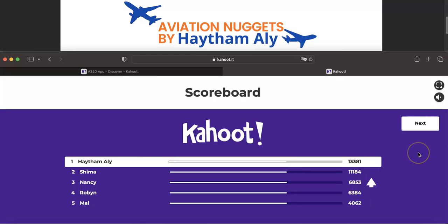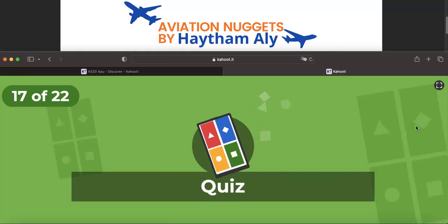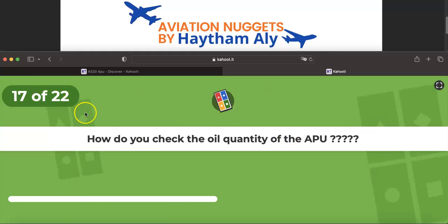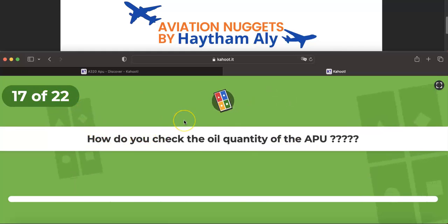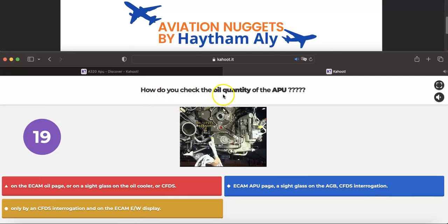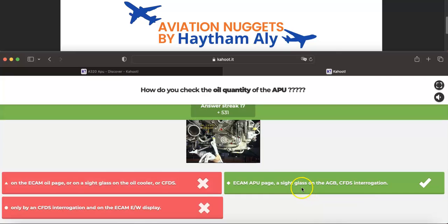Next question. I hope you enjoy these sets of questions. Question 17 of 22. How do you check the oil quantity of the APU? On the ECAM oil page, on a side glass on the oil cooler, or by CFDS? ECAM APU page, a side glass on the AGB, or only by CFDS interrogation on the ECAM engine warning display. The right answer is ECAM.